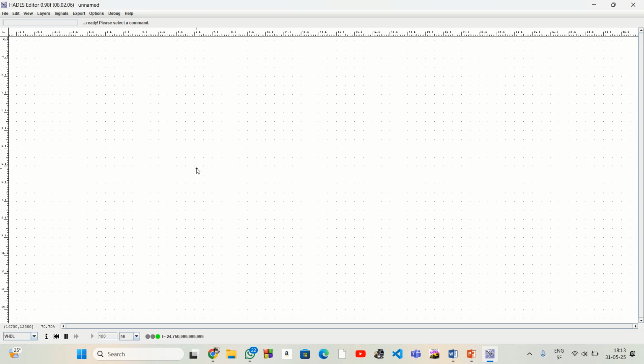So the next thing that I need to do is to bring in my latches. I'm working in 3 bits, and that's why I'll be bringing in 3 latches here. So I'll come to create flip-flops, and then I will use DFFR.